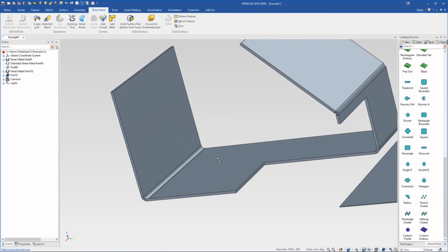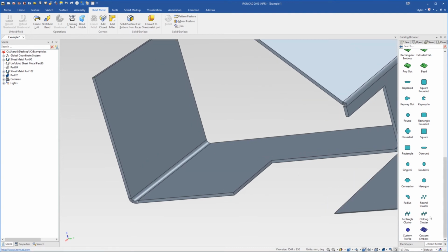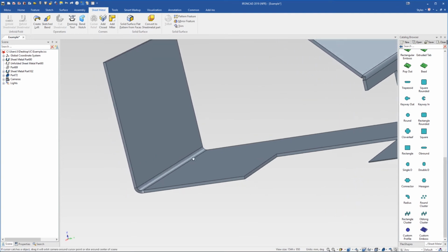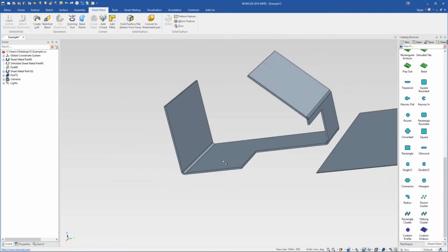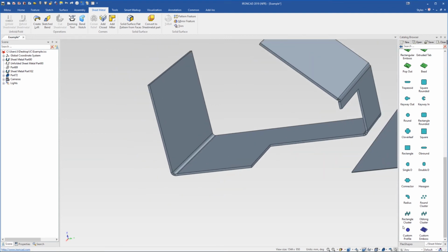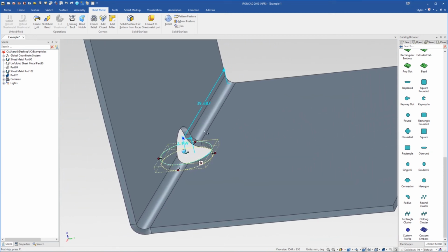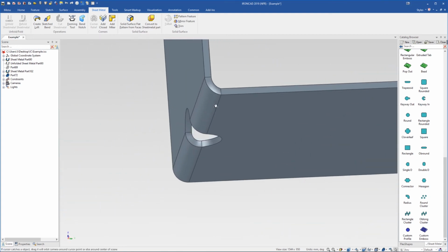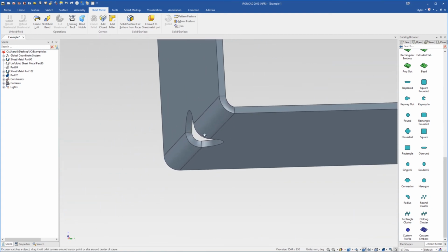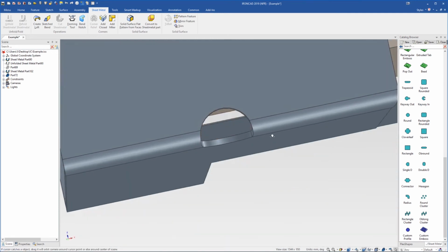One other tool we'll go into here before we go into our 2D drawings is just the Custom Profile tool. So this is good for editing the holes that are cut in flat pattern mode. So you can see here, if we drag and drop this out onto this bend, it'll actually cut a shape in the flat pattern. So that shape will generally be very hard to draw. If we tried to draw that in 3D, it would kind of be a combination of two cut cylinders.